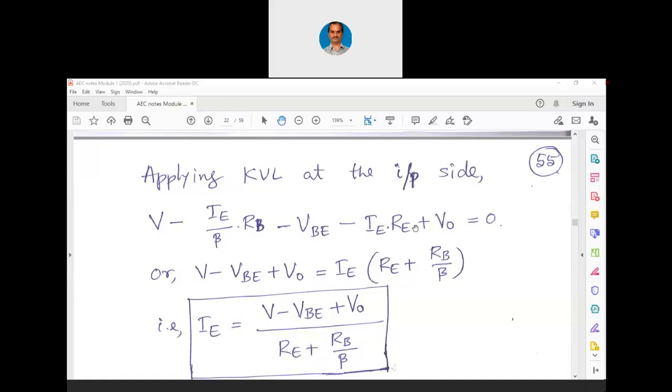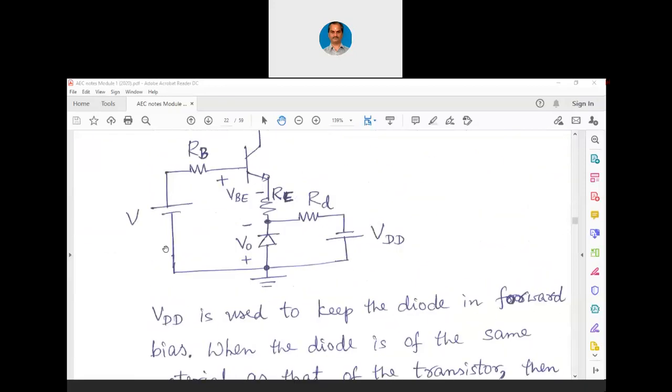You can see V0 we have written in this as plus symbol, because in the circuit when we go from negative to positive we use a conventional sign as plus. When we go from positive to negative, that is a loss there in the circuitry or a voltage drop there in the circuitry. For that we use the sign minus.